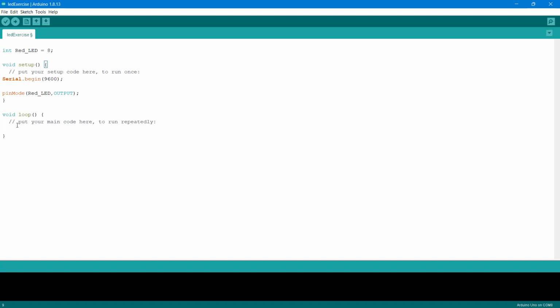So our LED is going to blink for 1000 milliseconds. To do that, we are going to write the code here. First we'll do digitalWrite. Okay, digitalWrite. Be sure of the spelling, so you can see how it spells. The W is caps, the D is small.